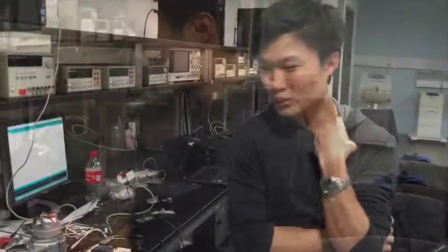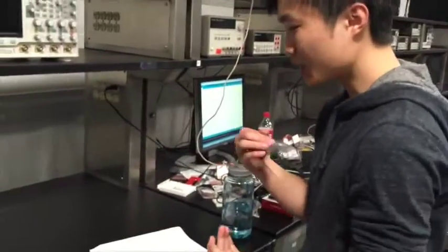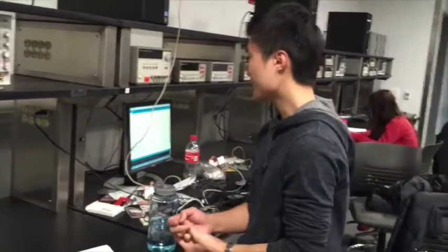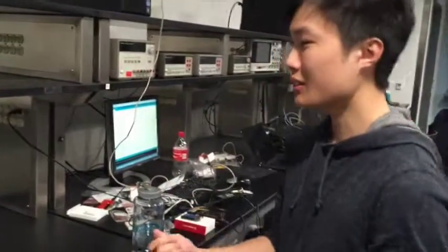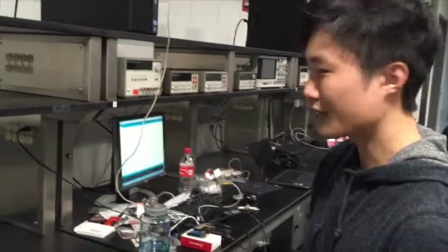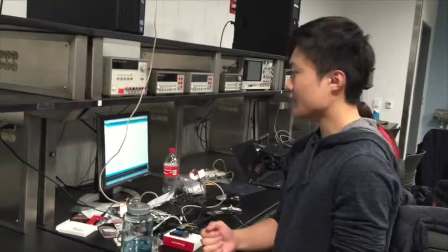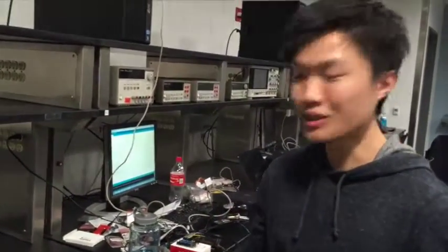In order to initialize the start of a packet so that MATLAB can synchronize the communication with the Arduino properly, we send a -1, which in our case we never otherwise use because all the other values are physical values.